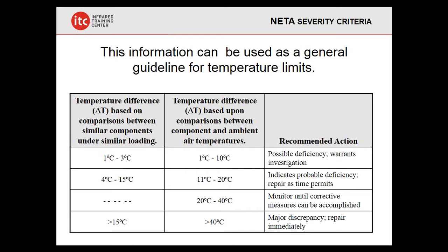Because what we find here at the end of the day, even after we've had training, is that temperature readings are not always reliable for a variety of reasons, whether it's emissivity, whether it's indirect heating, like we showed you earlier in this presentation, whether it's convective forces, such as winds that are cooling off objects, resolution-related issues, and the list goes on and on. Things that these temperature tables don't address. NETA just gives us these numbers, but doesn't say what the limitations to actually getting those numbers might be. And while these numbers might be based on a fully loaded circuit, they don't take into consideration all the things that we just talked about.